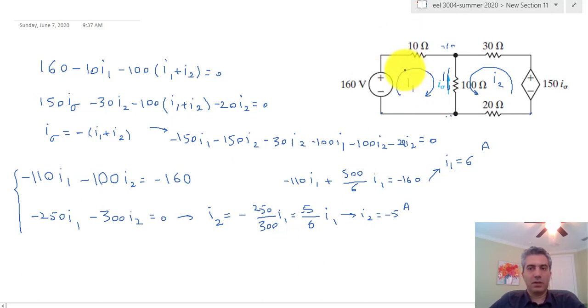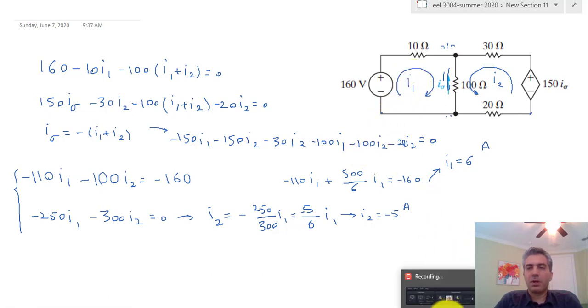So these results are all compatible, consistent with each other. And the currents that you calculate using these are going to all turn out to be exactly the same. The values for potentials are different depending on where you choose your ground, but the currents are going to have to be the same.